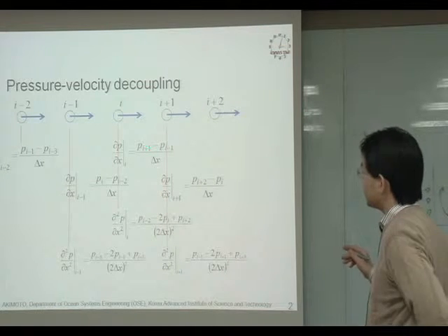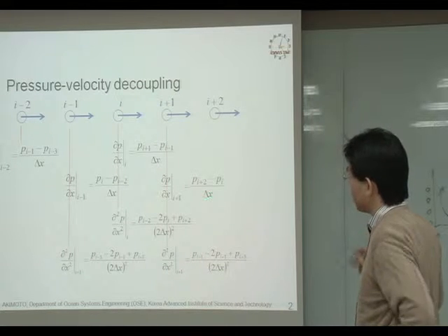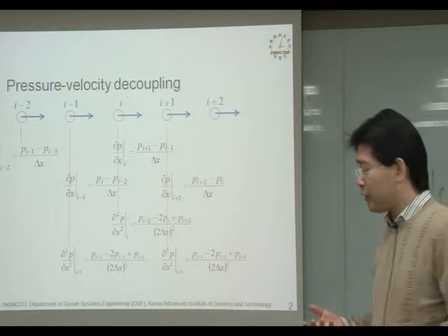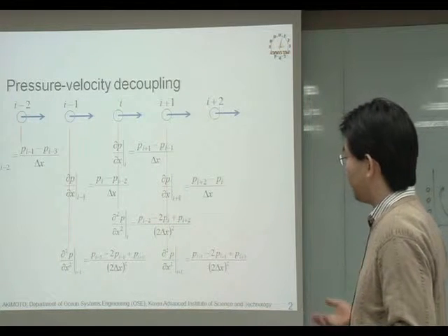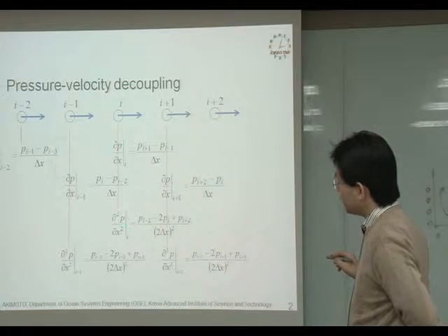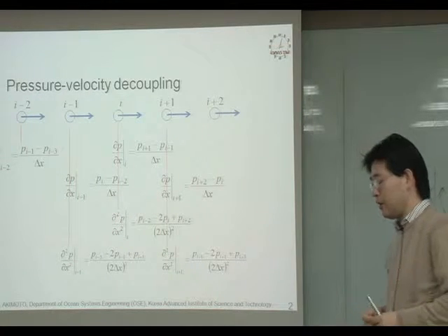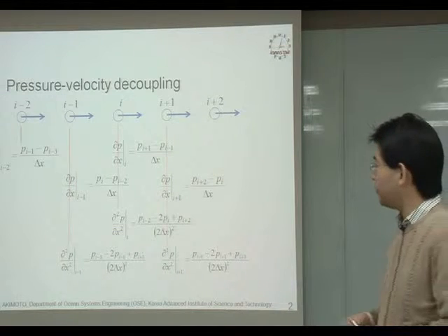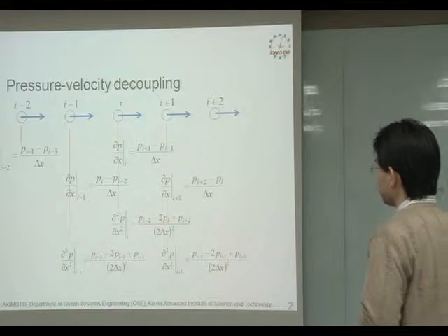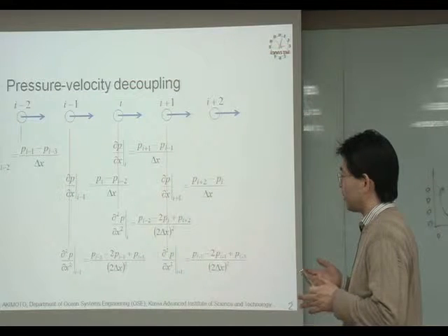It is because the gradient indicates the increase of velocity driven by pressure distribution, and the gradient of the pressure gradient indicates the divergence of the pressure-driven velocity increase. It should be compared to the actual divergence, and it should be cancelled.